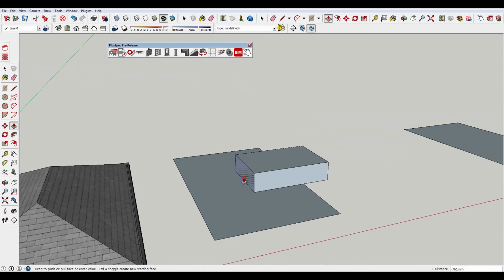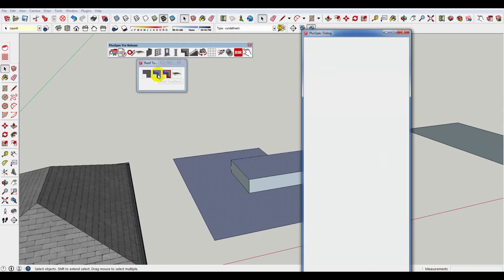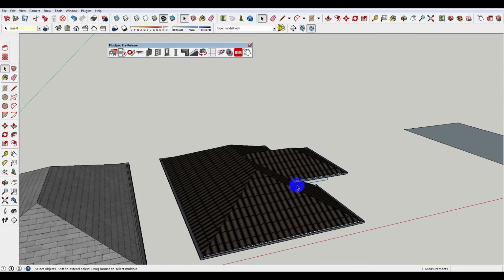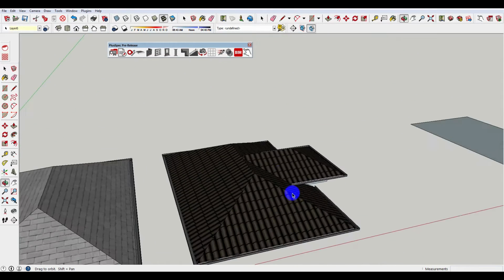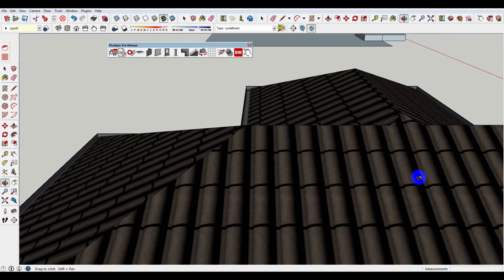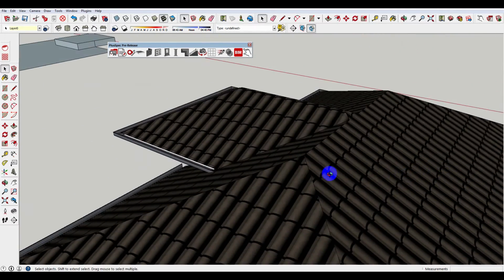Now there's a good way to mess around and see what your roof's going to look like first. I'm going to lower that down a touch, select this one here, go to the roof tool, select roof and face, submit. Okay, now you see the roof is actually starting to mesh in. So it's a good way to figure out your geometry and how the roof's going to look.